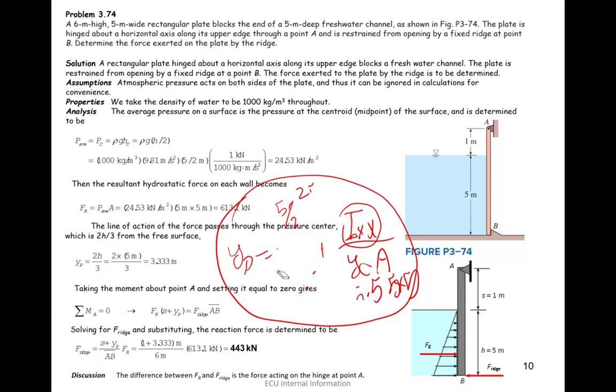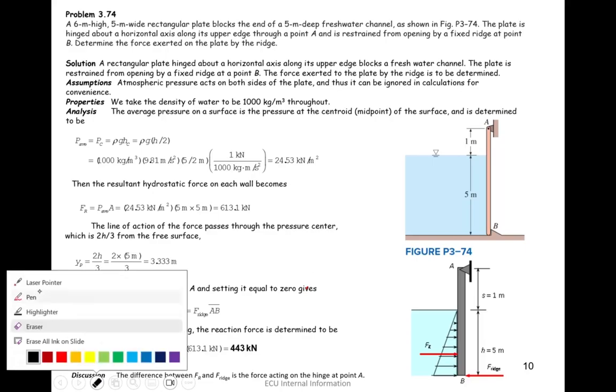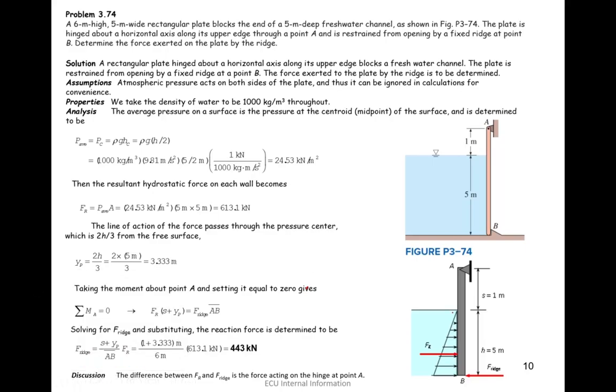This is one way, from the formula, which hasn't been used in this question, but what has been used in this question is that we can also work it out from the pressure prism. What is the pressure prism? Imagine this is the distribution of pressure which extends to that side as well.